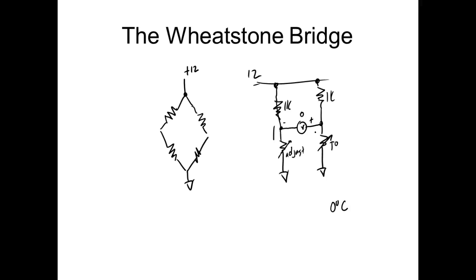Then we put weights on it, and then we set what we call the span. So what you do is you start off by zeroing out the scale. We put calibrated weights on there. We carry like 100,000 pounds worth of weights. We'd put it on there and tell the thing to weigh 100,000 pounds. We'd lift it up, because anytime you adjust the top, you move the 0, right? And you just keep zeroing it out after that.